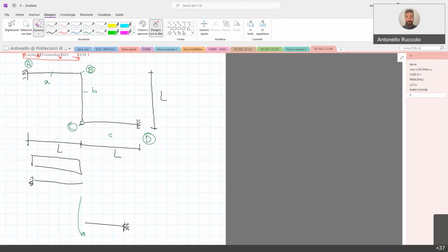because I have to draw again. I mean, the beam A will tend to deflect downward. The node has to have the same rotation between beam A and B of 90 degrees. So it will be something like this. The node C can go downward, but cannot go right or left, because the beam C is actually rigid.